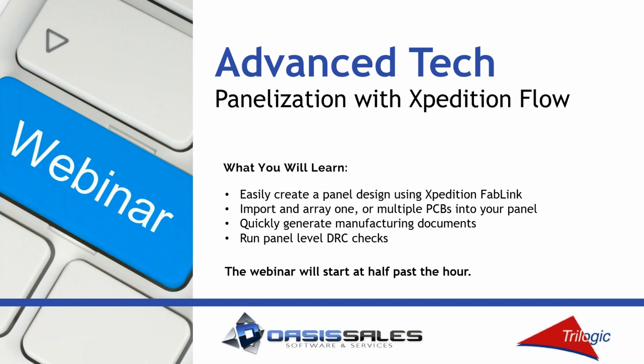What we can do within the FabLink and Xpedition Flow is easily create that panel design directly from the PCB. So we'll see that this is always going to be connected directly to your design data. This can be pretty powerful because if you make any changes during any aspect of the PCB design or the panel design, those changes can be reflected automatically and brought into the panel design. So the panelization process can be happening while there's some last minute changes happening in the PCB design as well.